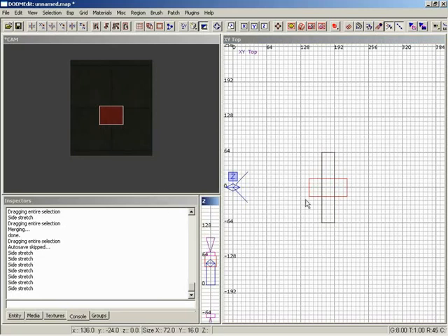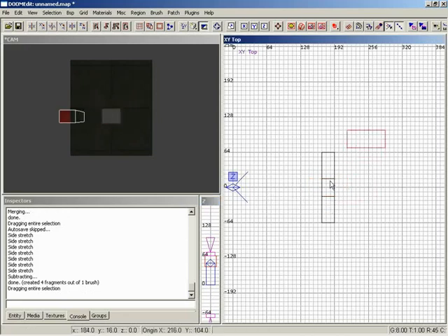So we've got one selected brush that goes through the other one, so it intersects it. And if we wanted to subtract out of this other brush, it's now as simple as hitting subtract. So subtract, and it doesn't immediately look like anything has happened, but that's just because it doesn't delete the brush that you were using for the subtract. If you move it out of the way now, we can see that we have more brushes.